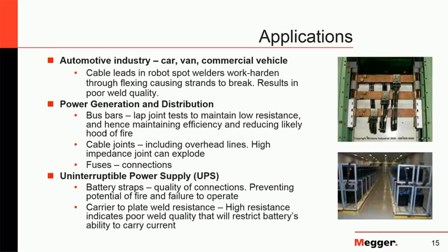Now, for example, this is a very interesting application on battery systems, on UPS systems. The battery cells are linked to each other with conductor bars called straps. These bars are subject to vibration, changing temperature due to the charging and discharging processes of the battery, and also, of course, to chemical corrosion. If only one of those straps in the system fails, then our whole bank will fail.